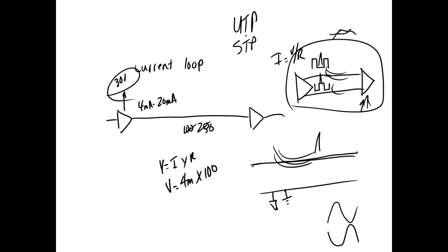It would amaze me if your cell phone is serial. It's probably the cable that you transfer information with, and also use as a charger cable. There's probably a 100% chance that it uses differential. It's unshielded too. So USB's a differential interface. Ethernet's a differential interface.